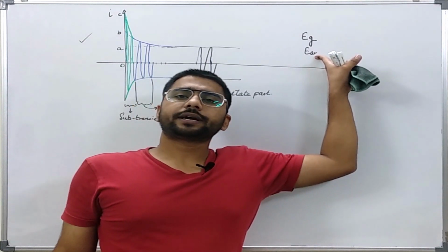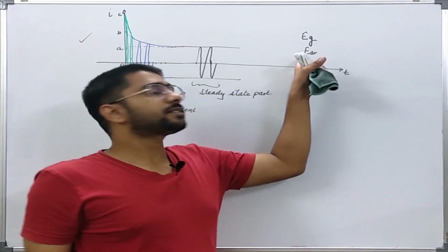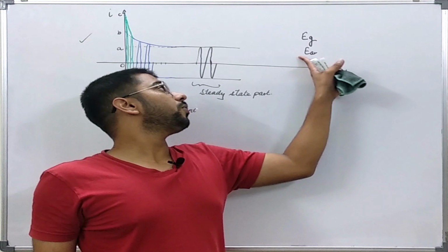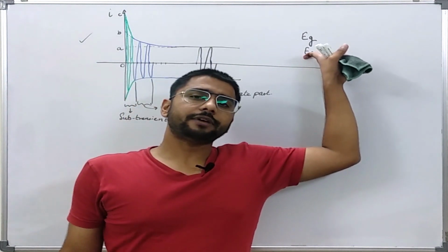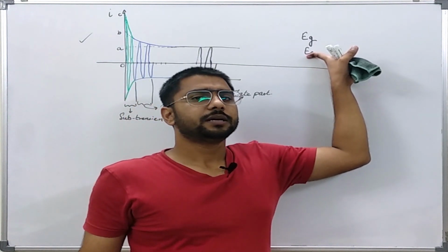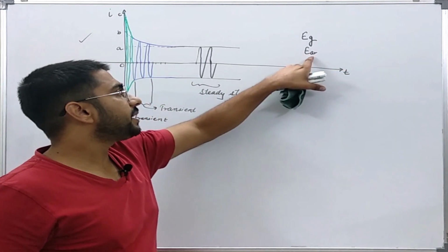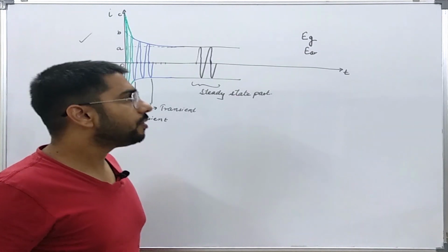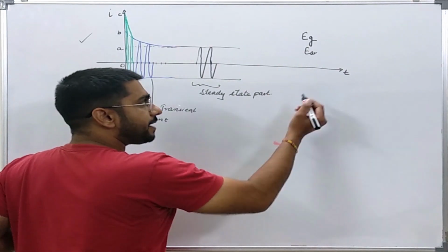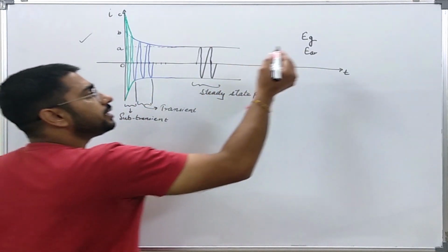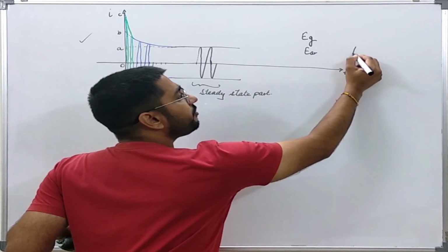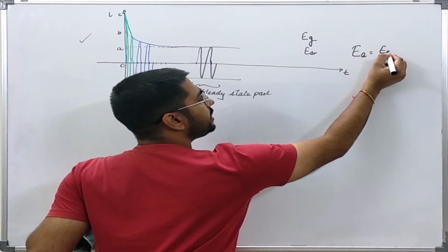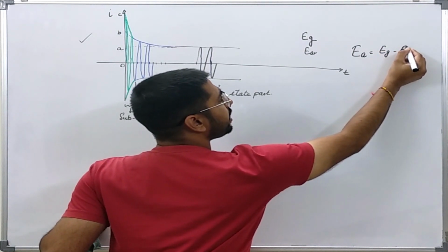So during a short circuit, since the current is 90 degrees out of phase, this thing is going to oppose. That we will see in detail when we study the synchronous machine, that this armature reaction induced EMF is going to oppose the no load generated voltage. So the final steady state value of the air gap EMF will be EA equal to EG minus EAR.